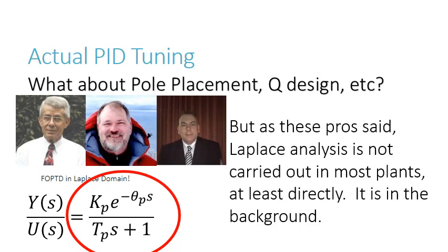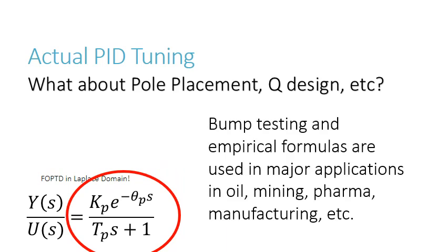But again, we're talking about like a mine or a refinery, and these gentlemen have been doing this for years, and it's just not used that much, according to them and according to other people that I've spoken to. And it just kind of intuitively makes sense as well. You're not going to be seeing a lot of Nyquist plots in a mine. Bump testing and empirical formulas, on the other hand, you've got many clever technicians out there that are very familiar with how to do this, and they've done excellent tuning, and they've got very efficient and profitable processes in these industries.